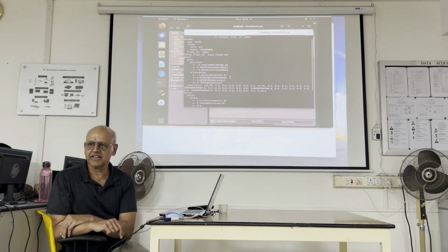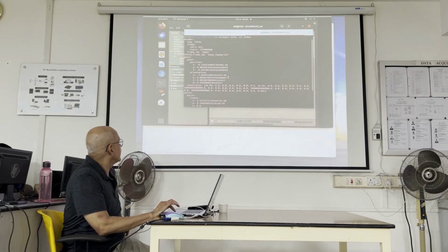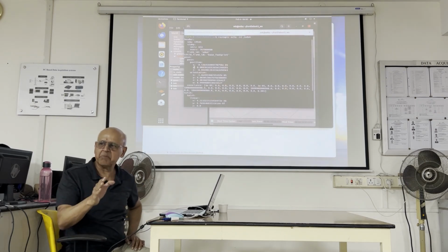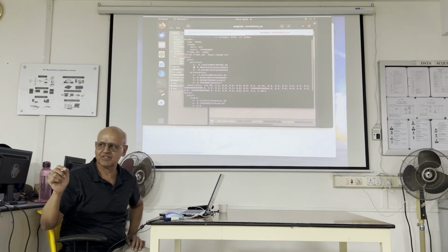Now, what is quaternion representation? It's made up of 4 numbers. The numbers you see are X, Y, Z, W, and you're going to get confused. You're going to say, is this X, Y, Z the same as that X, Y, Z? It isn't. It is the first 3 numbers of the quaternion representation. W is the last of the 4.